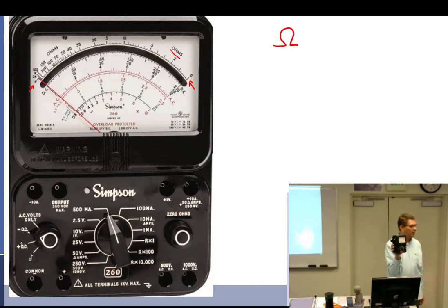See? Okay. When you recalibrate it, do you leave it in the 0 position? You have to recalibrate it to 0 every time. After I 0 it out, I can disconnect my leads, and I'm ready to start measuring. Don't touch that knob. Once you set it to 0, don't touch it again until you switch settings. Even if I went to measure volts and go back, I'd recheck it.